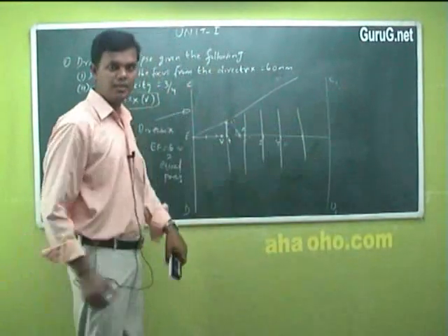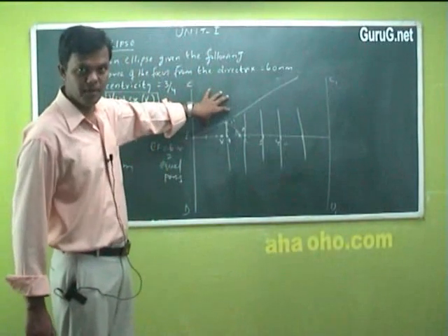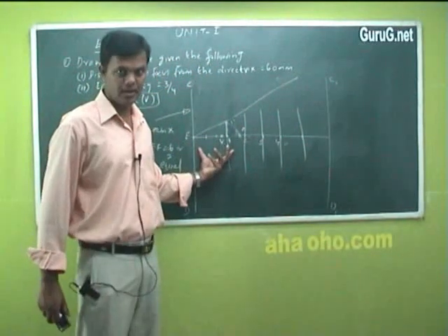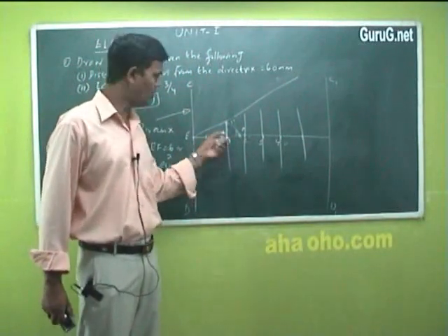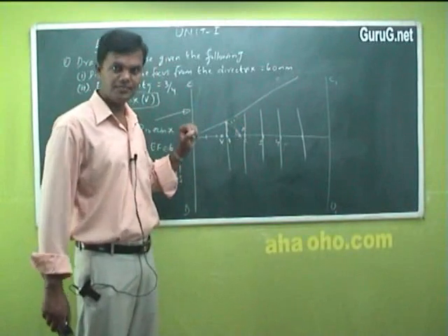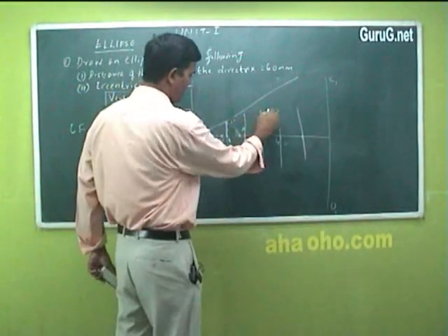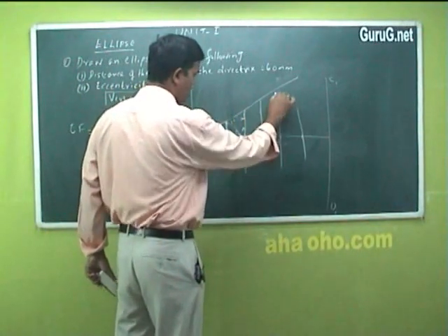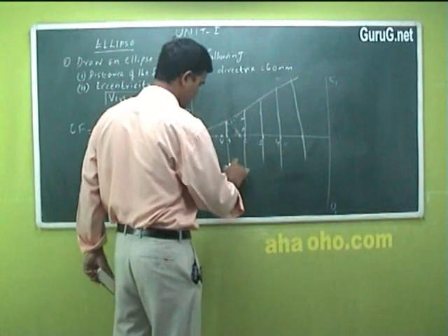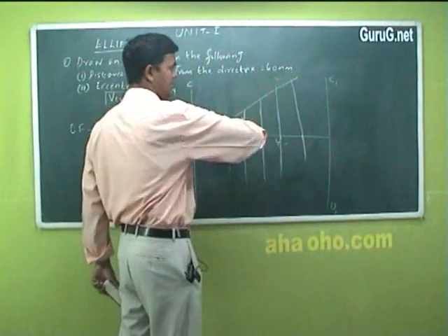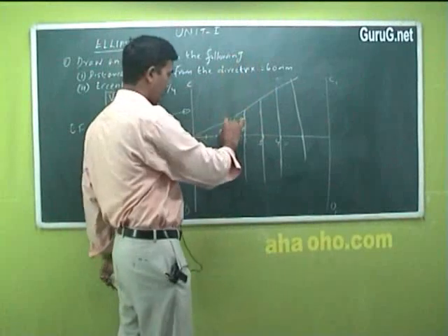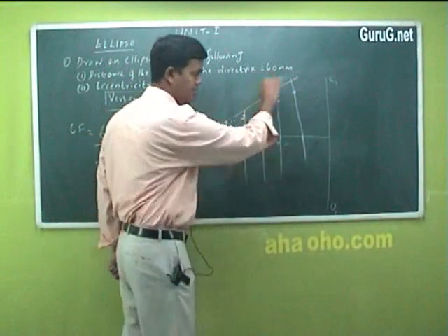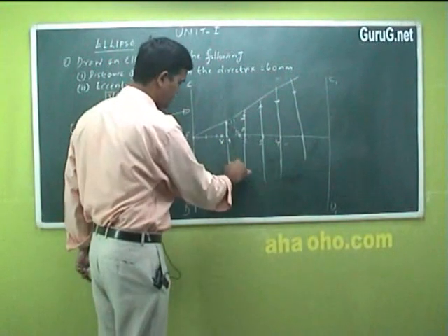It goes on like this, because I am drawing on a board. If you make it on a sheet with the actual distance of 60 millimeter and an eccentricity of 3/4, you will get a better sketch. Is it fine? That is better. So you take point by point, and when you take it, you will get a cut arc. You have to join this to the top. This inclined line, you need to join through every point. This is the first one, this the second, it comes like this, the third goes like this. It forms the curve, and the opposite side also.